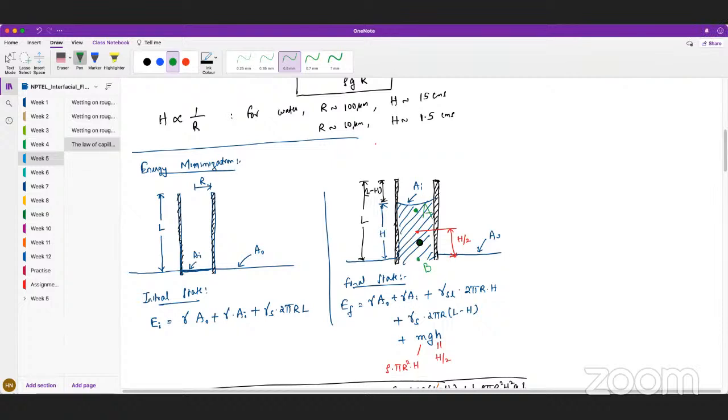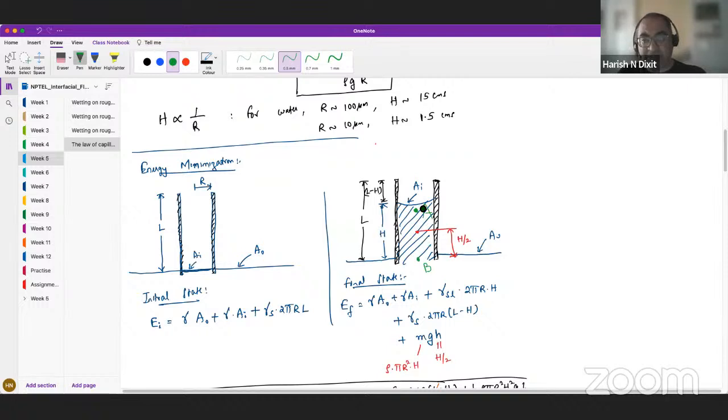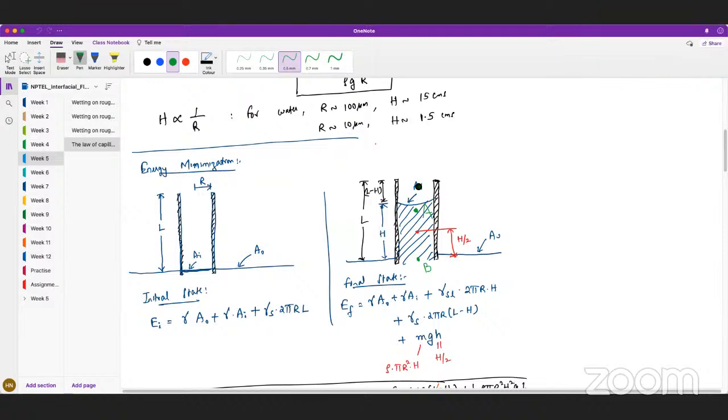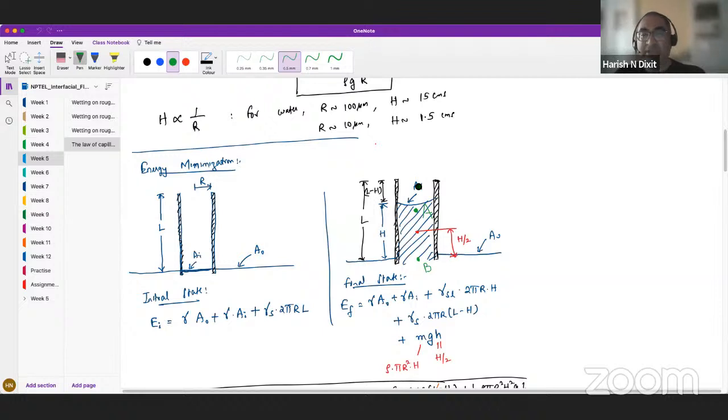Yes, sir. So now what we are trying to say is that when the fluid rises through the meniscus, its pressure is actually lower than what it would be if we do not consider velocity. If we do not have velocity at all, then the pressure at A and B and above can be simply related by hydrostatics and surface tension. But the moment you have fluid in motion, its effective pressure has decreased. And because its effective pressure has decreased because of its motion, the atmosphere will be able to do a better job at pushing it down. That's one way to think about it.